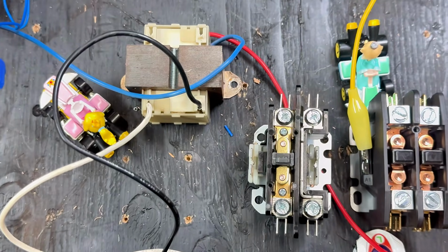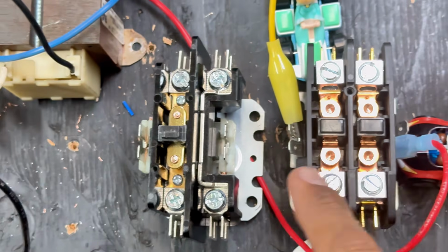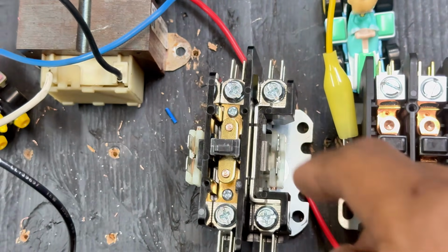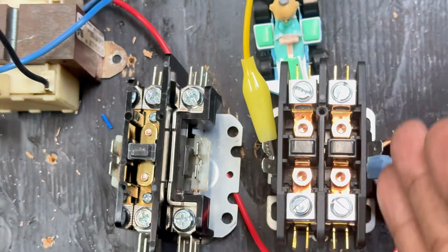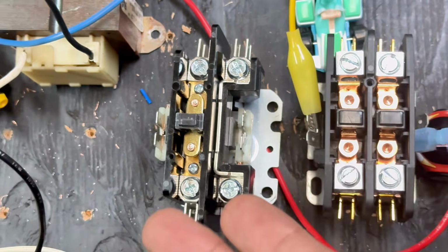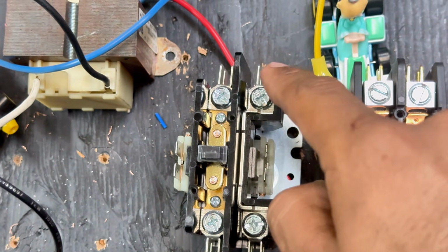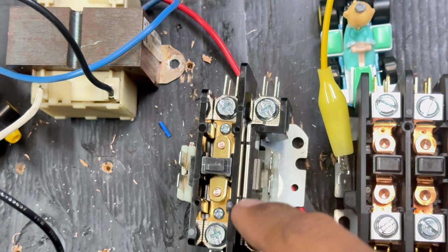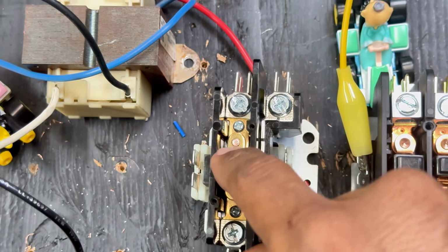All the contactor is, if we were to look at it, and let's see if we can get closer, you see you have one pole and two poles. So this has two poles. I like to refer to them as freeway lanes, like on a highway, you've got a first lane and a second lane. So you've got two lanes here, two lanes here. But if you look carefully at this lane here, there's nothing interrupting power. It's just a straight path from here, boom, boom, boom, you're there. On this one, though, to go from here to here, there is something in between.